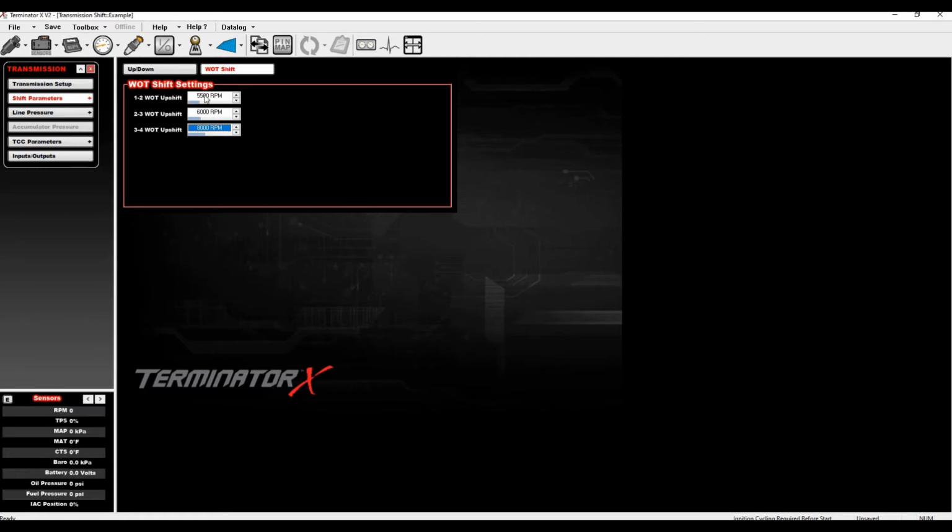So let's say on our 1-2 it got to 6,600. Okay, if I really want that to be 7,000 and it happened at 6,600, I need to add 400 RPM to this number roughly. And it's not going to be perfect every time, but you got to make sure you aren't ending up in the limiter. So if I add 400 to this, we're going to be at 5,900. And let's say that the 2-3, it only had a 300 RPM swing off. I asked for it at 6,000 and I got it at 6,300.